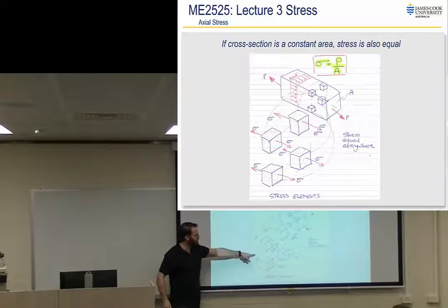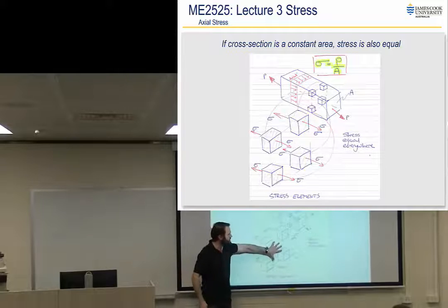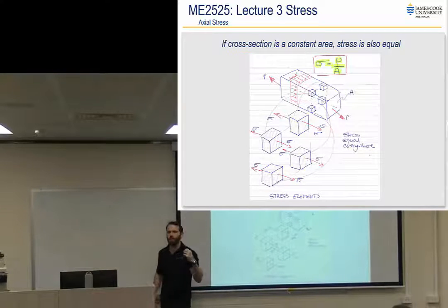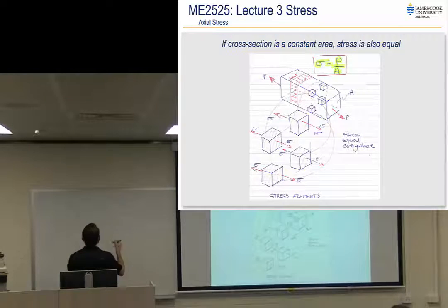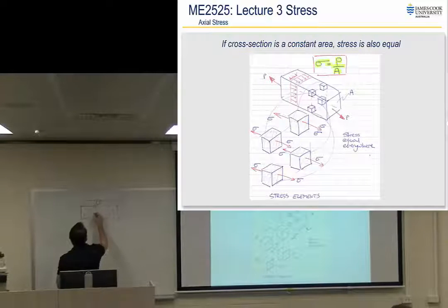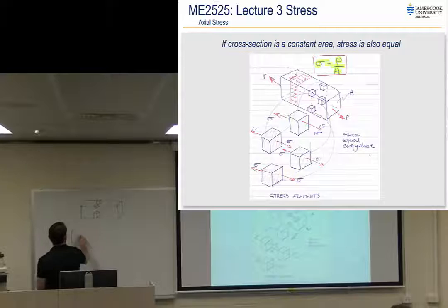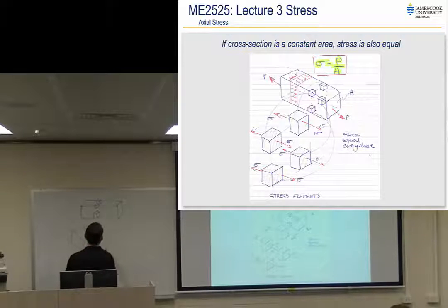If you look at my drawing here, it's very clear to me that these are the same elements as those. And I'm not going to confuse a front face with a side face or a top face when I'm adding those vectors. For example, if you were to draw a beam like this and say, I've got a stress element here and one here and one here, and then you change your aspect and you start drawing them like this, one here, one over here, one down here, something like that.